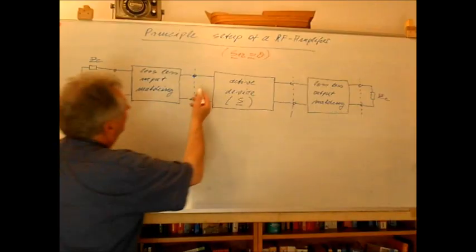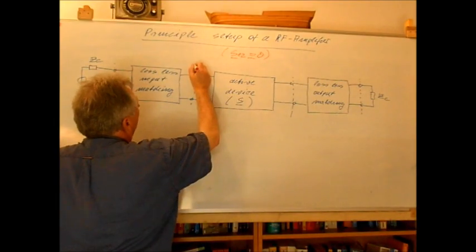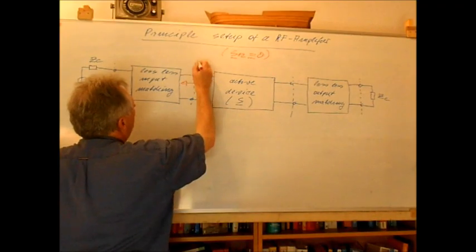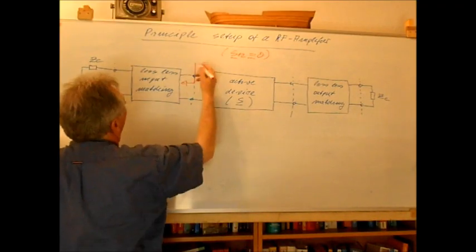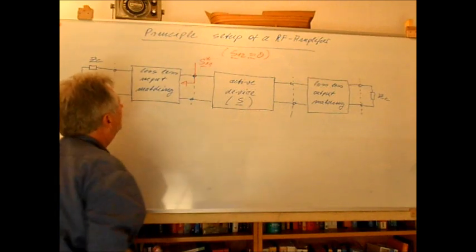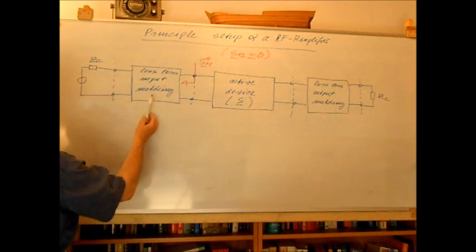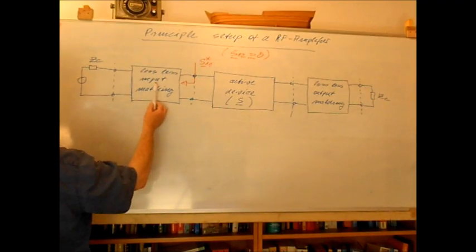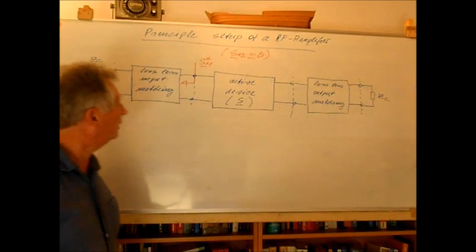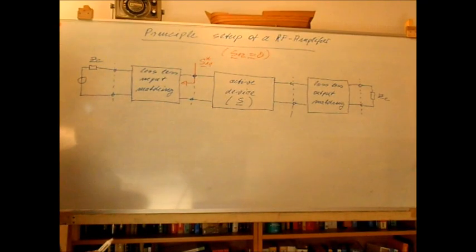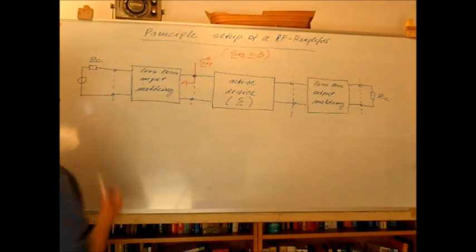So then we saw that we can get the maximum power gain if we see into this section of the circuit a conjugate complex. And how can we realize this? This we can realize if I have a lossless input matching network, and we saw, for example, in the first section in our transmission line theory with the help of the Smith chart how we can realize a lossless input matching network.